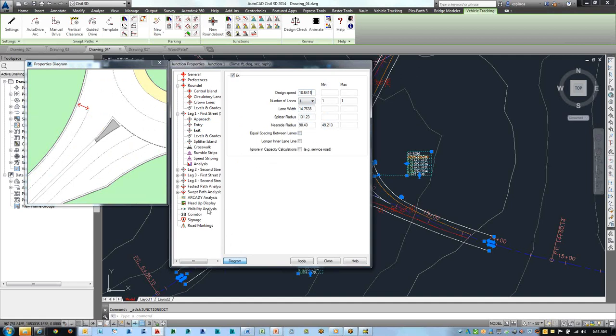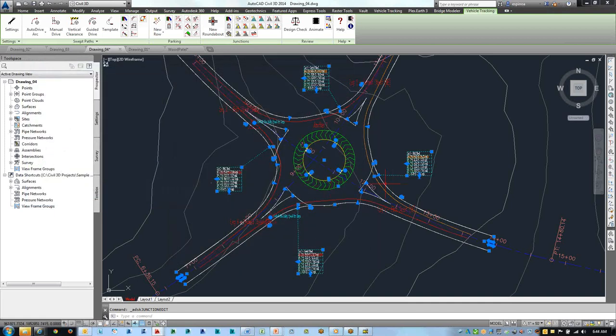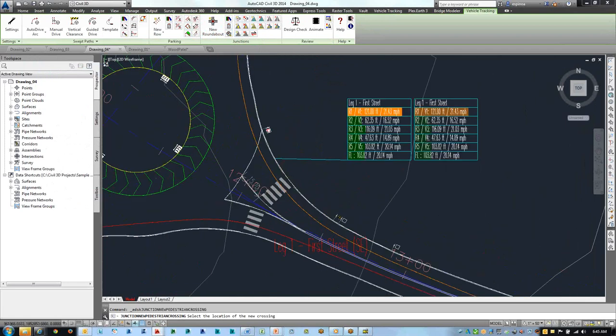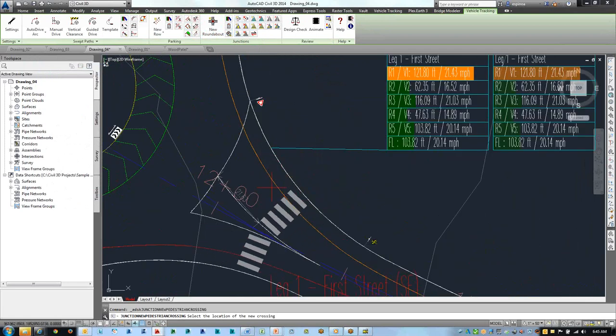Secondarily, coming down, let's go ahead and close that for just a moment. If I need to after the fact, by having that item selected, I'll come back up to the ribbon and I'll basically create a new crosswalk. So as I drop in this crosswalk, you can see I have control over the placement of this crosswalk. Now before I physically drop it in, I wish to point out there is a yield sign up here near what would be considered the limit or commit line.